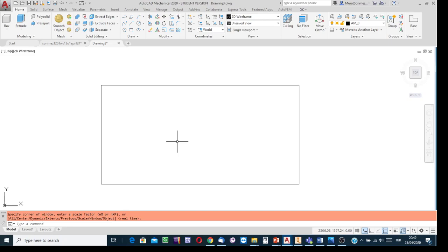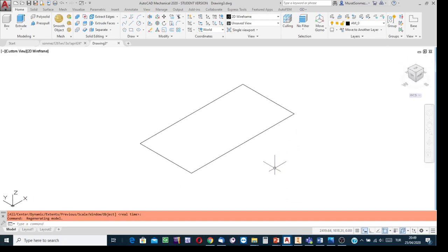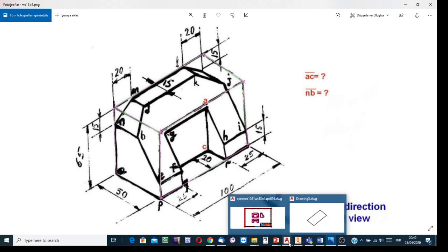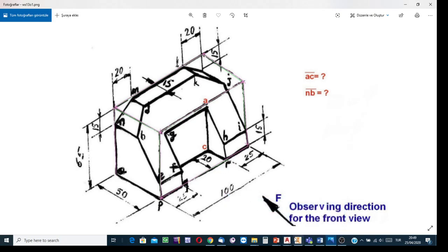Okay, and then after having the first sketch, for my convenience, I'm going to tilt this drawing. I can do it by clicking on the corner of the orientation cube or cutter symbol. Okay, and see the third axis, the z-axis. Now the xy plane is just the plane in which I have this rectangle, and in the z direction, yes, I have this worksheet, this pictorial figure on the worksheet. Okay, I'm going to create the prism first, the rectangular prism.